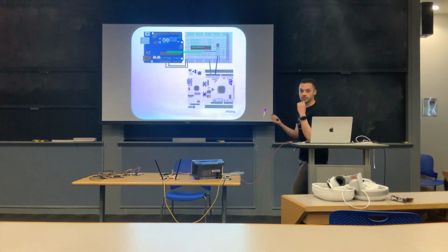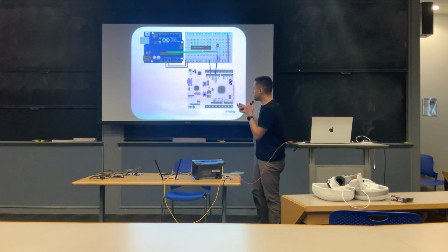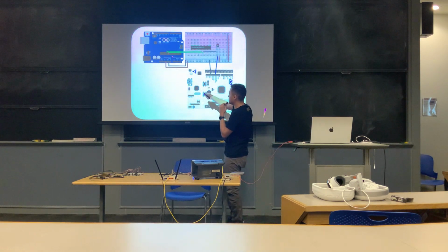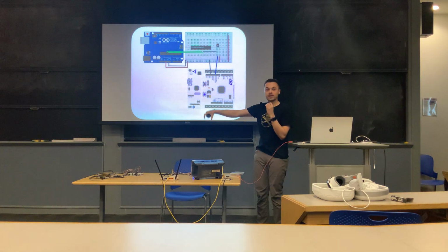And so here's an overview of what the setup actually looks like. Here's the Uno board, and I don't know if you guys have used Unos before. What you can actually do is pop the chip out. Normally this is where your processor would sit. What I've done is I've taken the chip out of the board and put it into a separate breadboard.